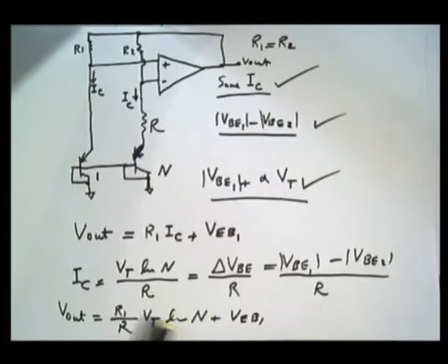One thing you keep in mind, here we have one VEB in the relation, that's very interesting, and then we generate some coefficient multiplied by VT to get that value of band gap. Okay, keep it in mind. So this is VEB plus some value multiplied by VT. That's why our reference is above VEB. I mean, definitely it will be above VEB, and it is shown that it will be around silicon band gap, 1.2 volt.